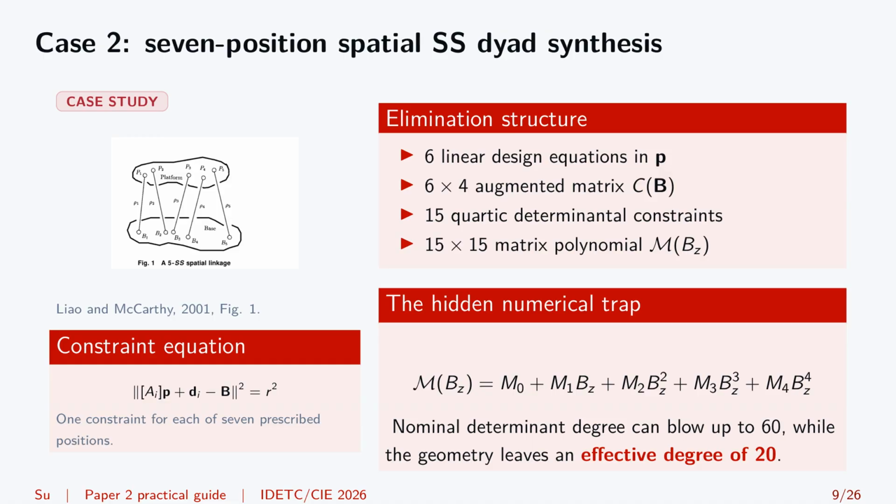The SS dyad case is different. It is a 7-position spatial synthesis problem whose formulation becomes a matrix polynomial. It is an excellent stress test. The mathematical object is documented, but expanding a determinant can create enormous intermediate expressions and severe numerical sensitivity.